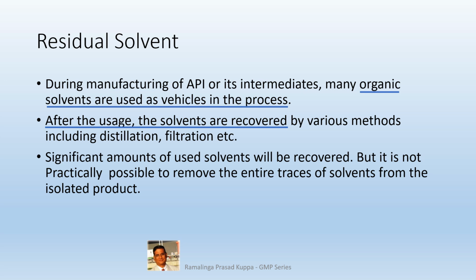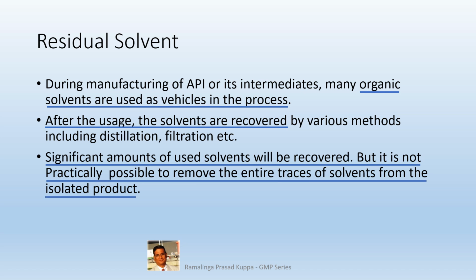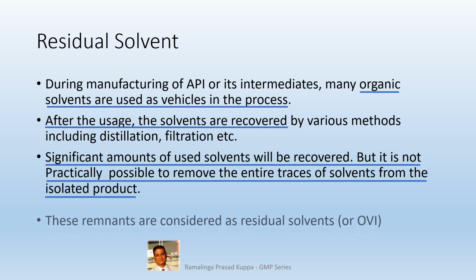Significant amounts of used solvents will be recovered, but it is not practically possible to remove all traces of solvents from the isolated product. It is not economical to drive out residual solvents completely. Also, it is not necessary to do so. So, some amount of traces of solvents will be retained in the isolated product.